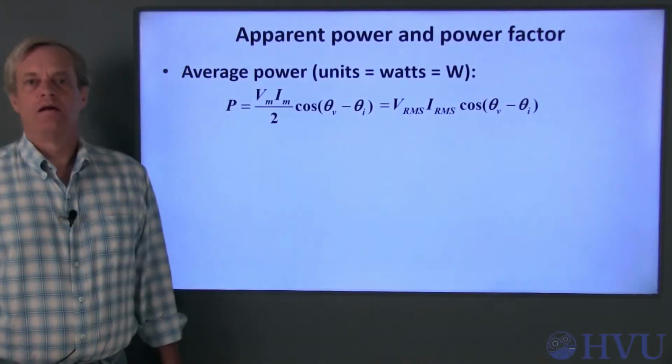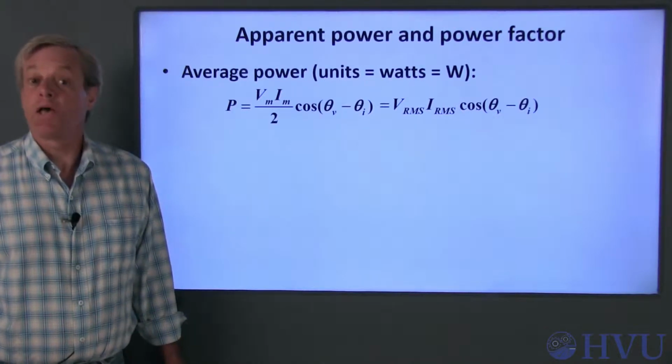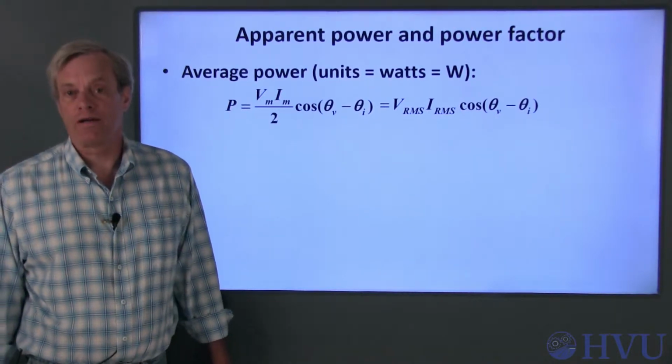As we've seen, capacitors and inductors don't contribute to average power. However, that doesn't mean that they don't have an effect on AC power, but we do need to broaden our definition of power. In this video, we'll introduce complex power, which has an imaginary component. Before we talk about complex power, I want to introduce a couple of new terms: apparent power and power factor.